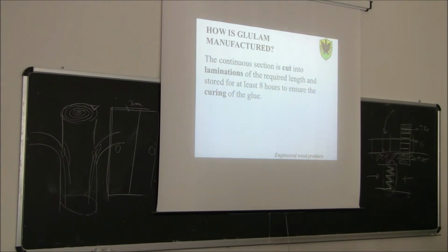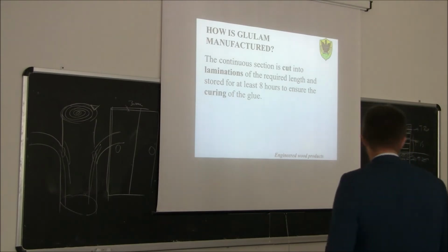Okay, now the continuous section is cut into laminations of the required length and stored for at least 8 hours to ensure the curing of the glue. So we need at least 8 hours to make sure that the glue of the finger joint will be cured.